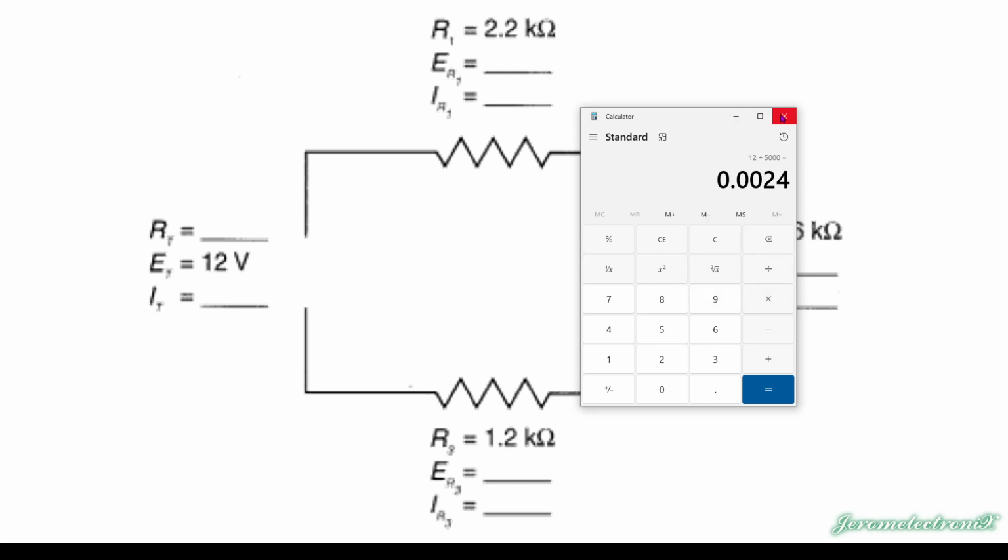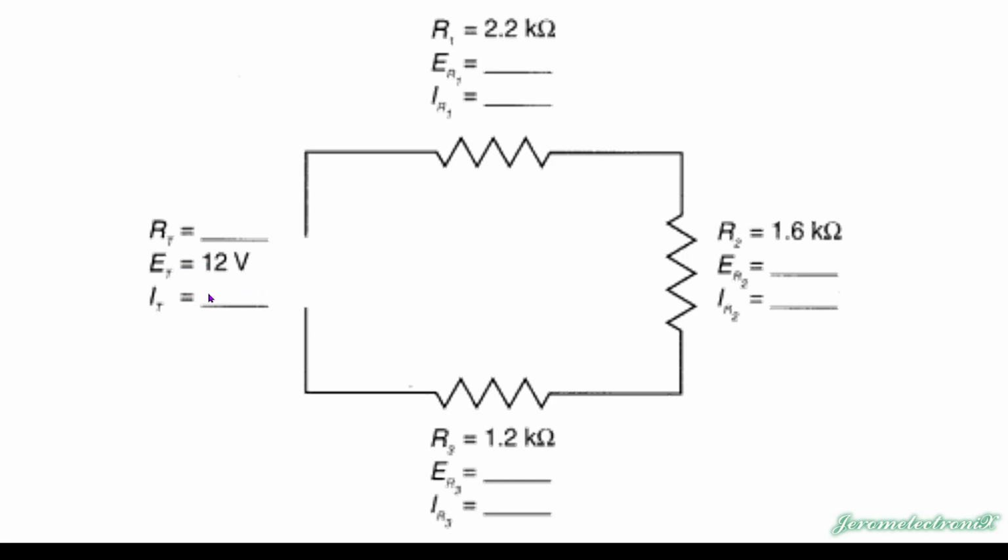Okay, so it's 2.4 here. And that means it's 2.4 amps all the way around. 2.4, that would be milliamps. It's 0.0024 amps, or 2.4 milliamps after you've converted into engineering prefix notation. And that's the same all the way around. And then you can take them out of prefix notation and put them into base units. In this case, it will work either way.